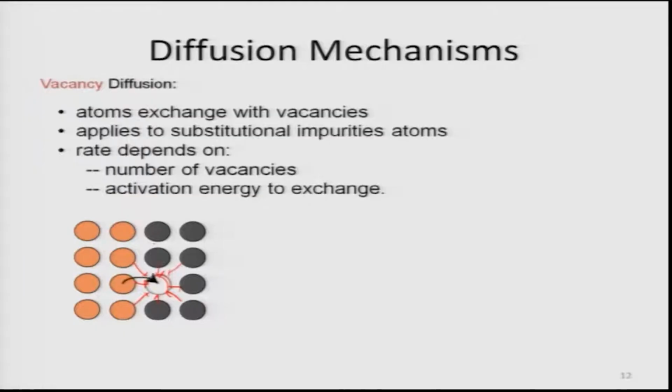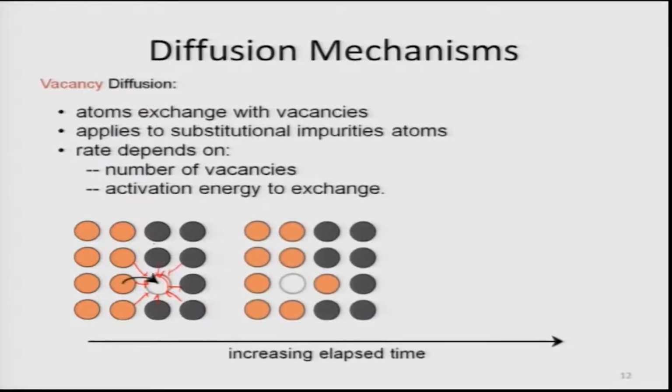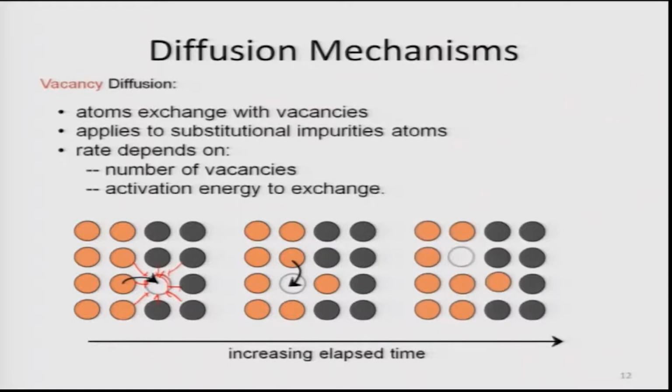Now we can also see here that these are the diffusions happening, as the black arrow shows: the atom has diffused from here to there, so the vacancy has moved also. If the vacancy moves, then another atom can move into the vacancy, and another configuration of atoms will happen, as the vacancy has moved above. So basically diffusion can also be treated as a movement of vacancies. The vacancy is moving from here to there, and in the process atoms are also interchanging their positions.